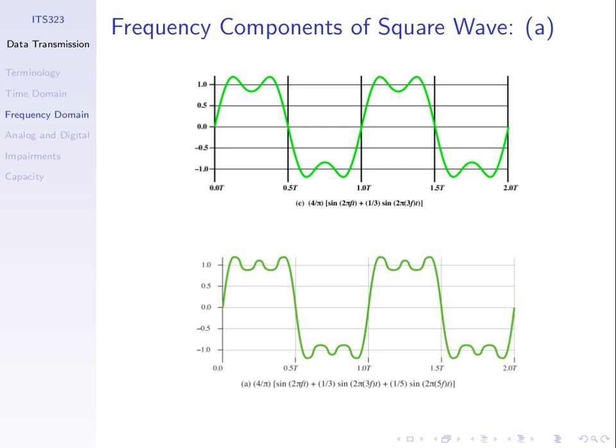What's the fundamental frequency of our signal? The fundamental frequency of this signal SA is 1,000, because the two components are both multiples of 1,000. 1 times 1,000, 3 times 1,000, so we say the fundamental frequency of A is 1,000. I'll simply write it as FA. That's also the frequency of signal A.